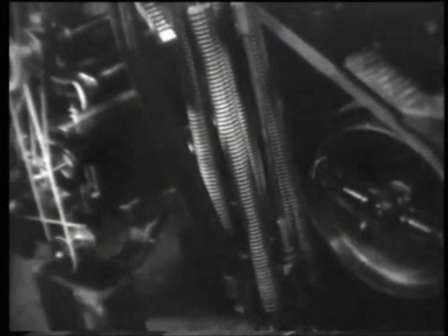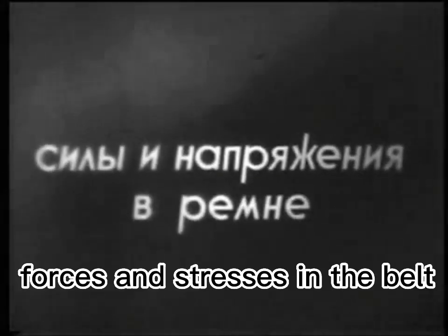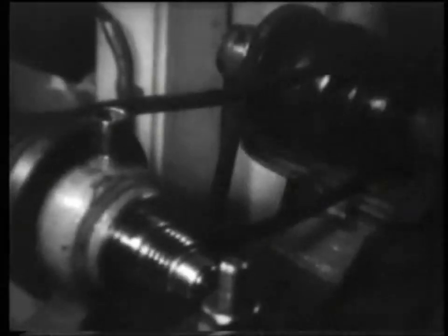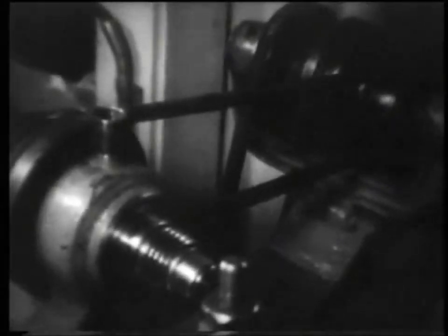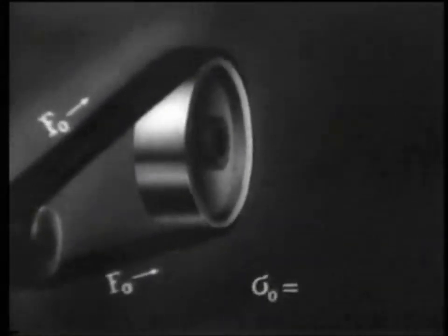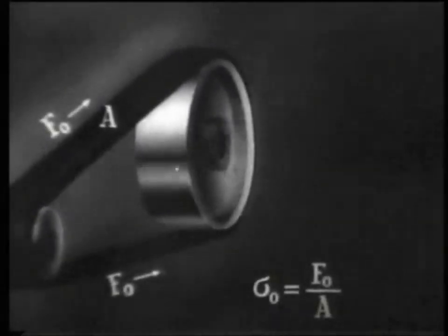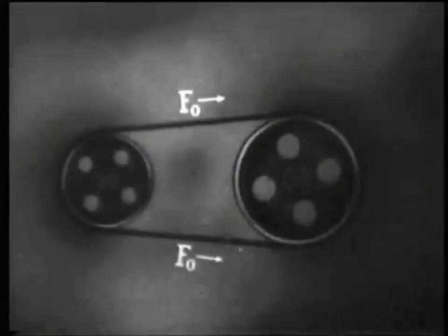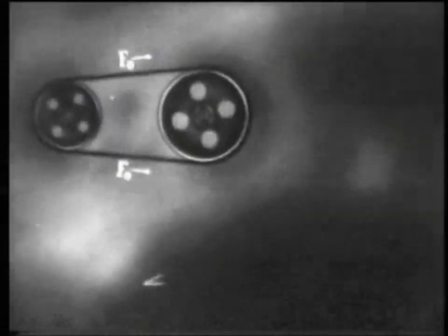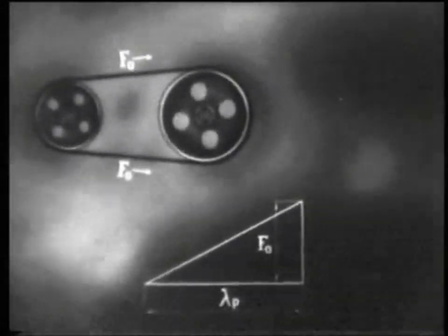For systems with a spatial arrangement of axes, round belt drives are convenient. Let's consider the basics of operation and calculation of belt gears. The tension required to create friction between the belt and the pulleys causes tensile stretching. When the belt is stretched by the force F0, the belt stretches by the amount lambda p, and the machine part is deformed in the direction of reducing the axial distance by the amount lambda d.